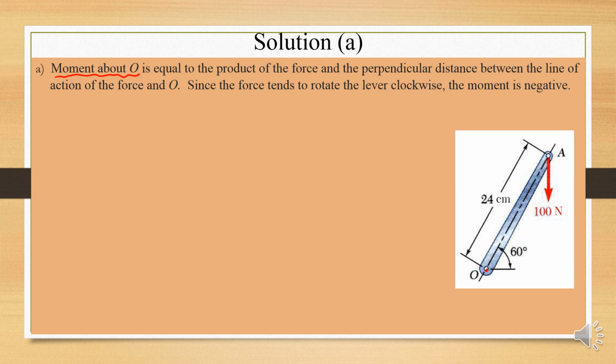The easiest way to imagine where the rotation is, you just imagine that you are locating a kind of wheel here at your reference point. So this wheel is being applied with the force in this direction, the same direction of force at A. Of course this wheel will turn in clockwise direction. Therefore, this moment will be a negative moment because it moves in clockwise direction.